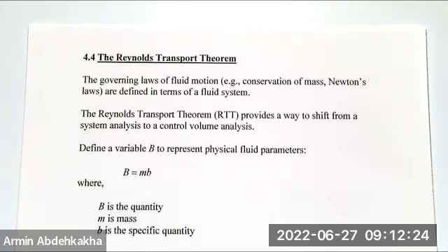Most of the time, if you have an unsteady flow, it's possible that if you track particles, you will have a different path line for that particle compared with the real streamline of the flow, because the particles are free to move, right? In general, if the flow is unsteady, they are moving inside of each other, and you know that these are different from the flow streamlines.